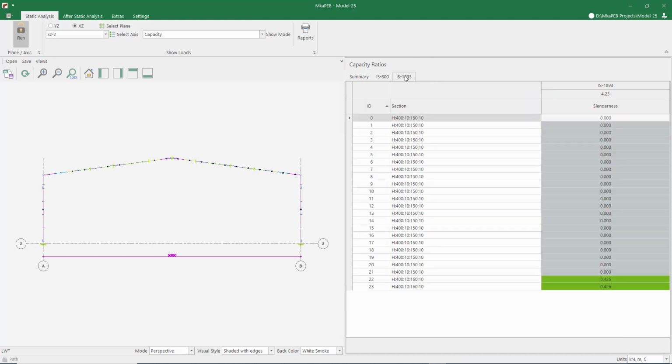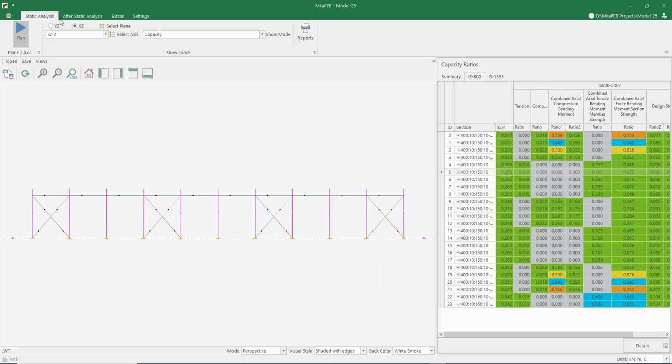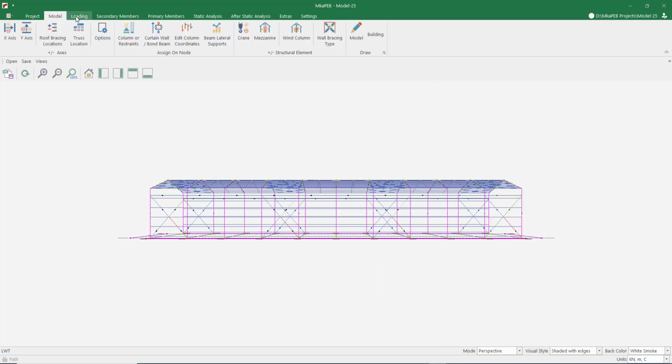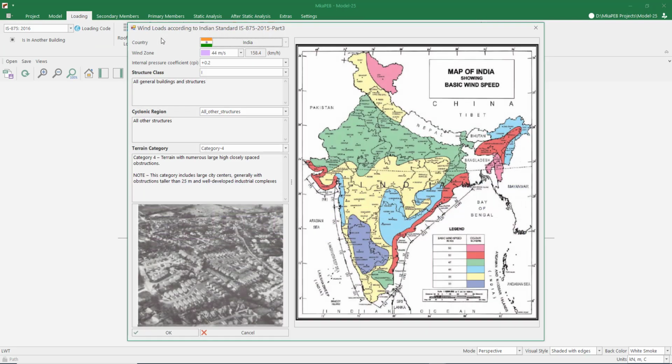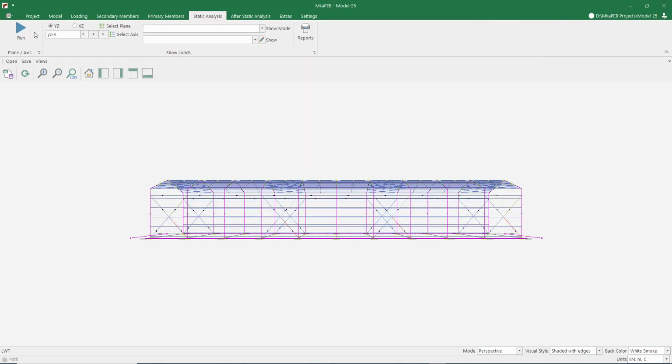In the earthquake regulation section, slenderness checks were made. We calculated with positive 0.2 wind load coefficient. We also need to calculate for negative internal pressure. For this, I first set the internal pressure coefficient negative 0.3 from the wind loads menu. I have to choose whichever option is more inconvenient.